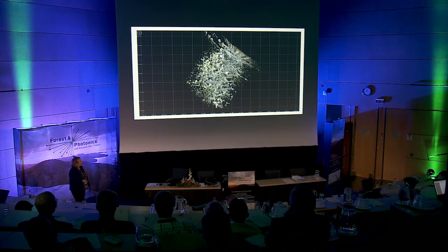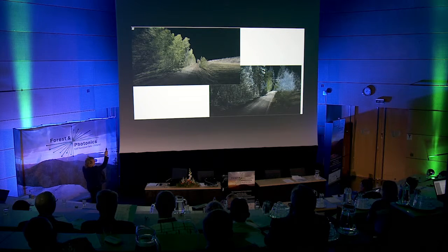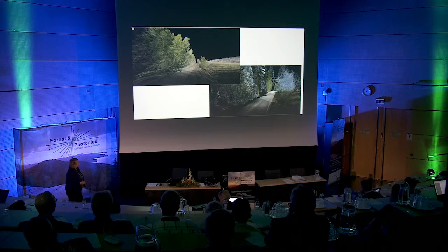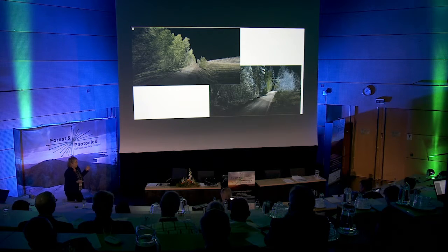And here's the forest, or the 45-year-old forest, sorry, from above. I mean, it's a mess of points, basically. It's colored with the RGB images. Little bit seen from the ground. There was a road going past it. So the UAV drone data is on your left, and the terrestrial LiDAR data is on your right. So you can see a difference. I mean, there are differences in density and things like that. And of course, I have to say here that we use a LiDAR that has multiple returns, so it penetrates more. If you use a LiDAR which doesn't, then you don't get this kind of data.